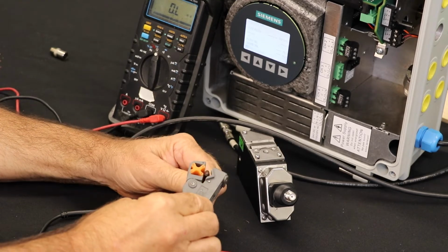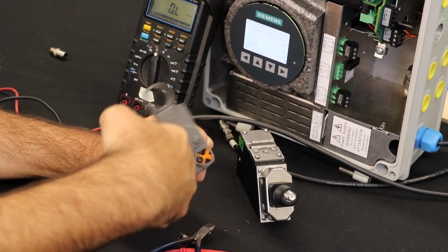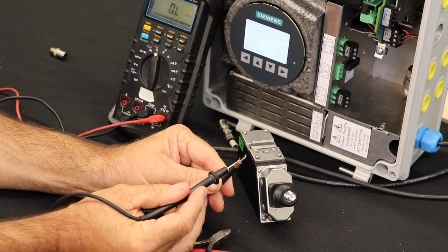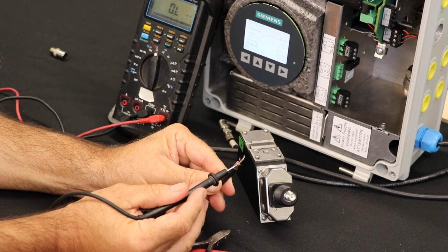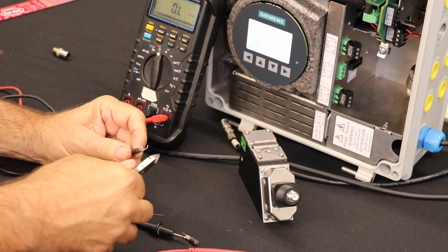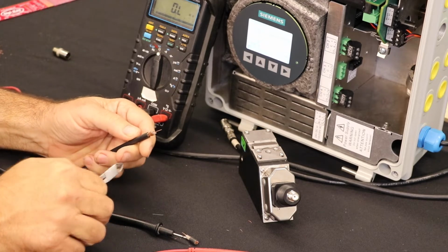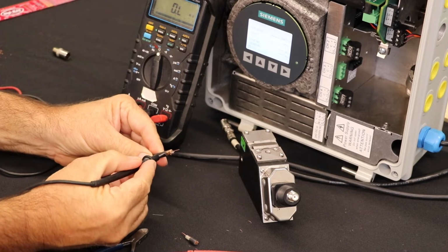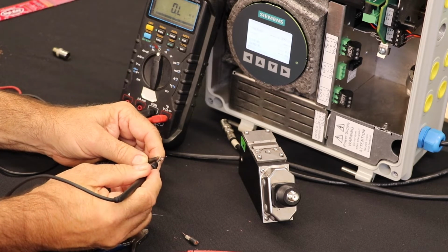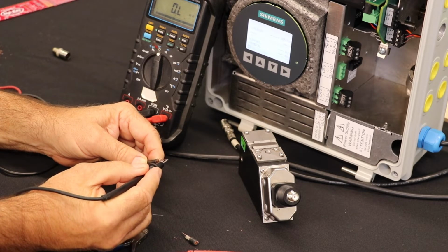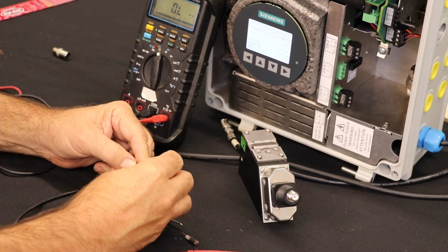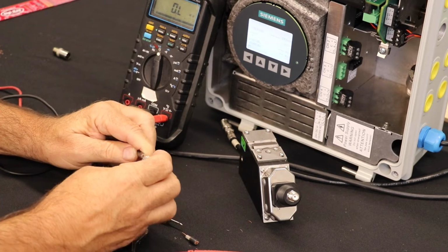And I'm going to use this tool to re-strip it. And this is what we should actually see. The braided material reaching from the outer insulation just to the end of the inside insulation with no whiskers touching the center conductor. Just trim this piece of center plastic if it's still there. The length from the outer insulation to the end of the inside insulation is 1/4 inch, and from the end of the inside insulation to the end of the center conductor is 3/8. And then first make sure no whiskers are touching the center conductor, and then just tighten this back on.